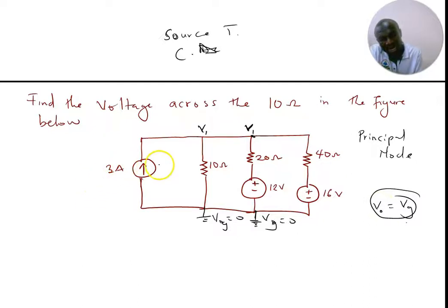So with this path, the path from here all the way to this side is having a current source, so we ignore it. But we show a current direction at this point. With this, you can show the current direction upward or downwards. It depends on you. But you just need to make sure that, like what we said when we were talking about KCL, all the currents shouldn't be directed towards one node. At least some should be entering and some should be leaving.